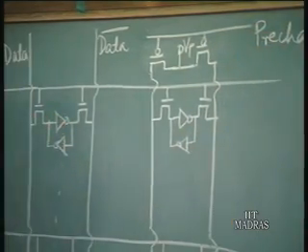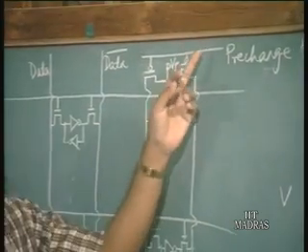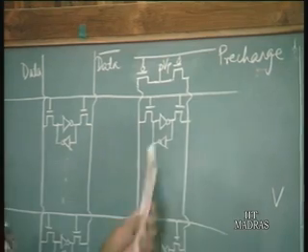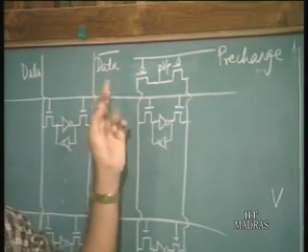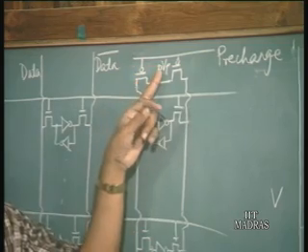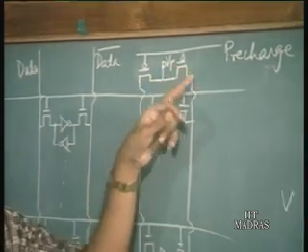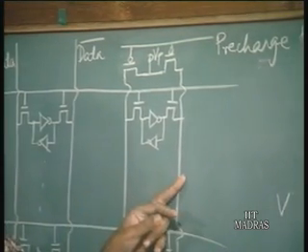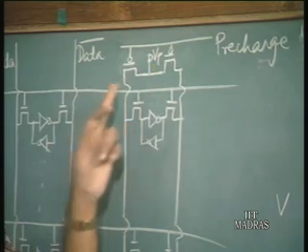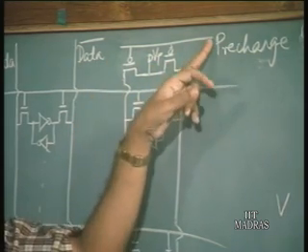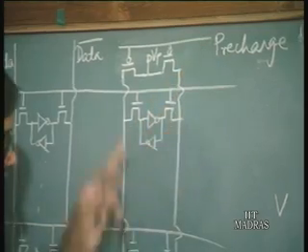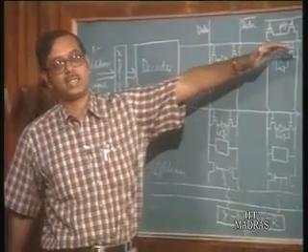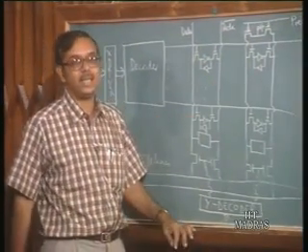So, again a two-phase clock is used. So, when the pre-charge input here goes low, these two PMOS transistors turn on, and this pre-charge voltage, which is available here, is now available on the data and data bar lines. So, the data and data bar lines are both pre-charged to this initial value Vp, the pre-charge voltage. Okay. So, when this pre-charge input is low, then both the data and data bar lines have the same values. Now, when we select a particular cell, the word line goes high, a particular cell is selected.